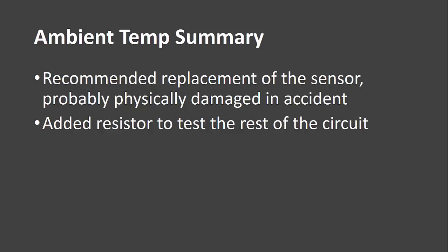I used to do a lot of Ford 7.3 injector tests. These vehicles would barely start or run really poorly in the morning when they were cold, and then once they warmed up, you would never know that the vehicle had an issue. So it's a classic bad injector. However, you just don't know which one because a lot of times they would not code.